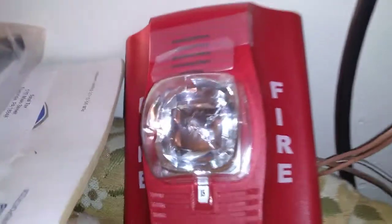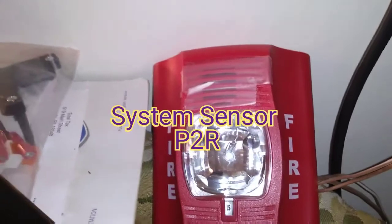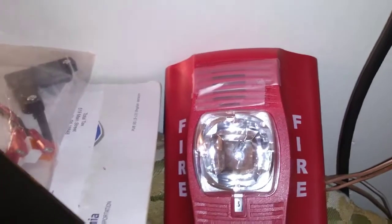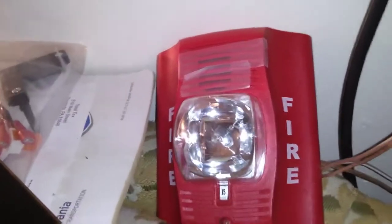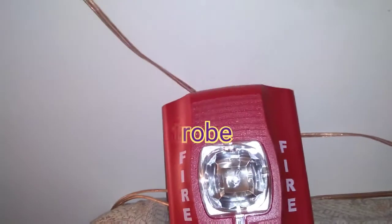Notification devices I've got right here. This is my System Sensor P2R, System Sensor Spectralert Advance. That's the P2R. I think P stands for piezo, 2 stands for it's a 2-wire, and R stands for red. If it's a P2W, it would be white with red fire lettering. This one here is a System Sensor SR remote strobe.